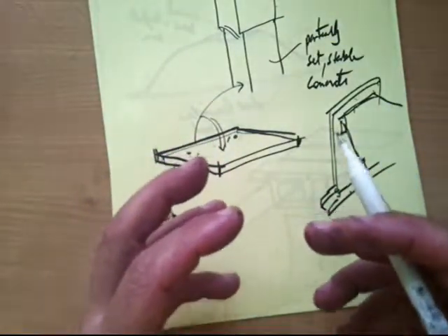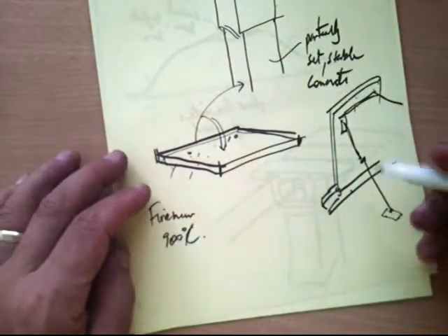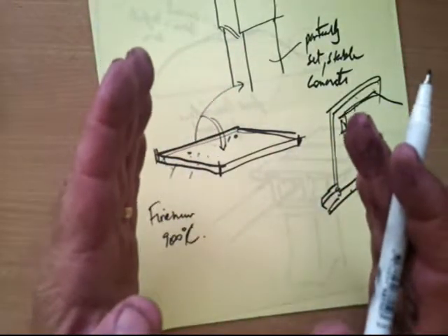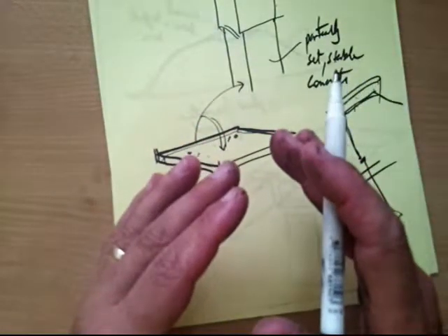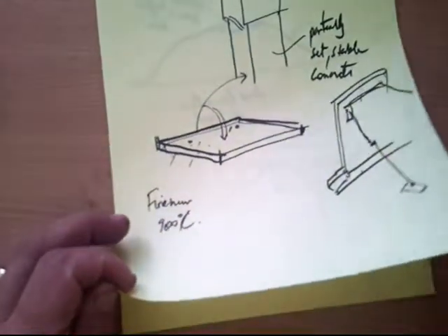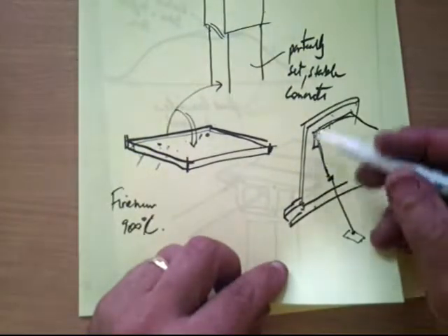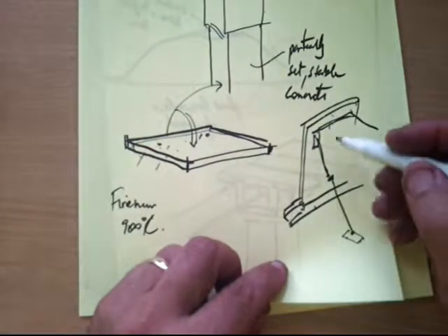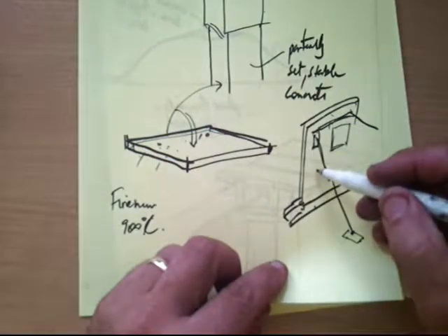It doesn't take long to reach that kind of temperature, and as it does, the steel progressively loses its strength, and at 900 degrees it will start to become plastic and start to collapse. So these whole tilt panels start to fold inwards or outwards, and they just become like a massive deadly deck of cards that just fall over and flop down. So there are some issues surrounding the fire hazards with these large buildings made out of concrete tilt panels.